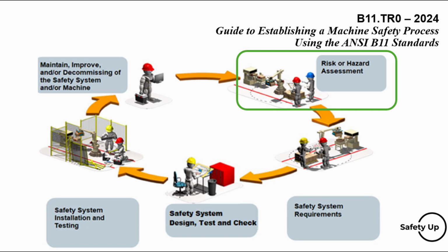The initial risk assessment is conducted during the conceptual design of a new machine or system. Also, a risk assessment is conducted anytime the machine is being modified or retrofitted, or the initial risk assessment is reviewed. During each lifecycle phase, machine limits are documented, tasks and hazards are identified, and risk is estimated and evaluated. Tasks may involve any number of reasonably foreseeable interactions with a machine or equipment based on the operation involved. Hazards may be mechanical, electrical, electromagnetic, chemical, radiological, etc., depending on the application.